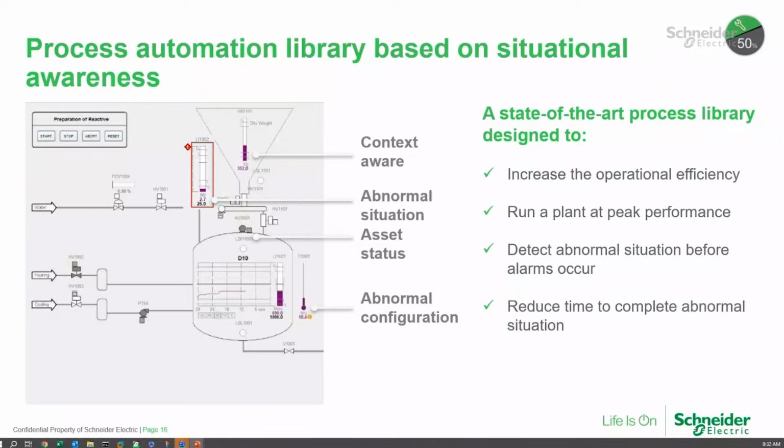So situational awareness, we used to call it grayscale when it first came out. It's called high performance graphics as well. Situational awareness is really kind of bland graphics, but color is used where it's needed to highlight anything, especially that's in an abnormal condition or an alarm condition.